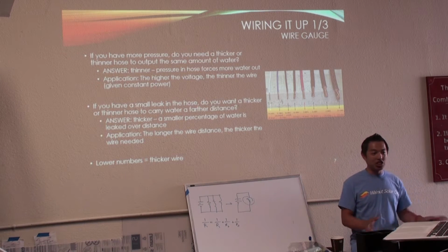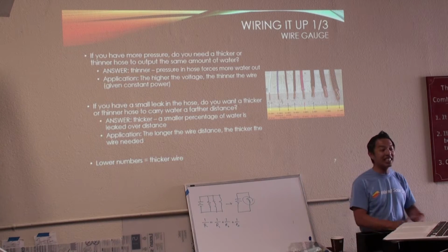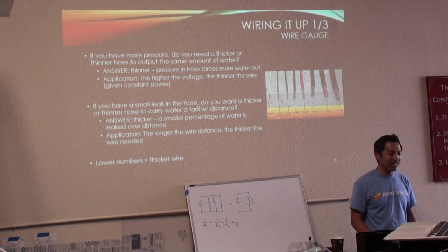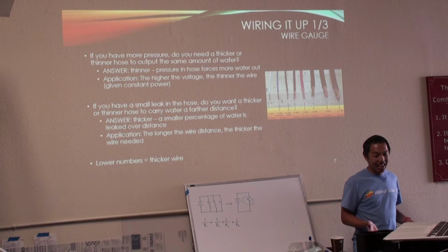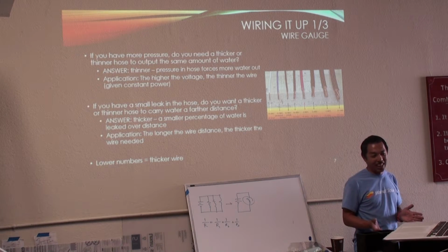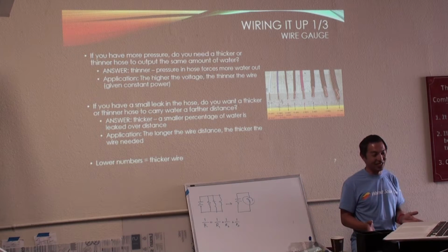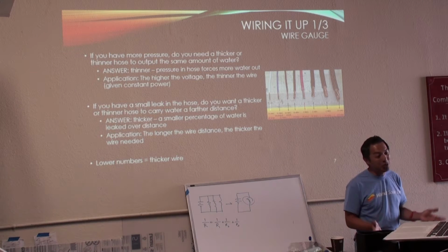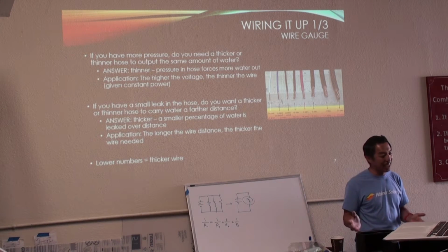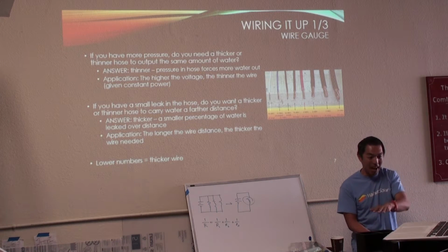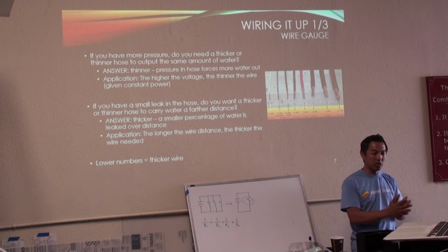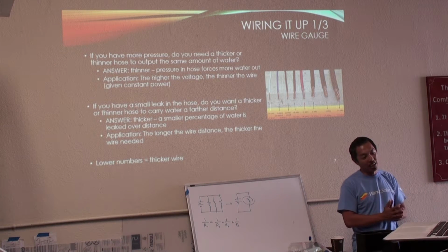If I wanted to discharge it instantaneously, and I stomp on the gas, I could theoretically get to 100 amps. I will not be running for a tenth of an hour, or 6 minutes. I'd probably run 1 or 2 minutes and then be out. The current could be larger than the capacity. It's just based on how long you're running that.